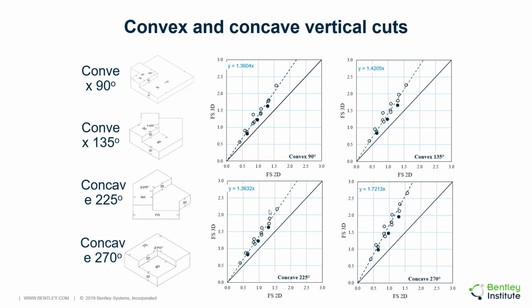And I guess we get a lot of questions about, well, isn't there just a standard difference between 2D and 3D analysis? And the answer is no. It's very dependent upon your geometry, your slip surface shape, whether there's anchors there, your loading conditions, your supports, a wide variety of things. And this just demonstrates the influence of simple cases of geometry on the factor of safety and demonstrating that you can have a fairly significant difference between 2D and 3D factors of safety.